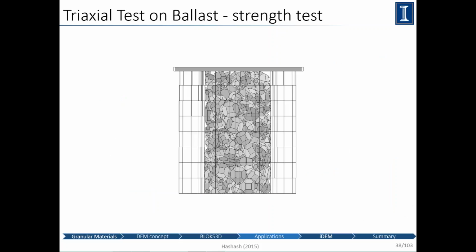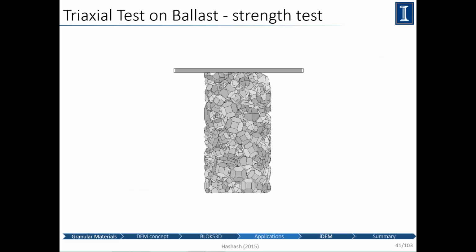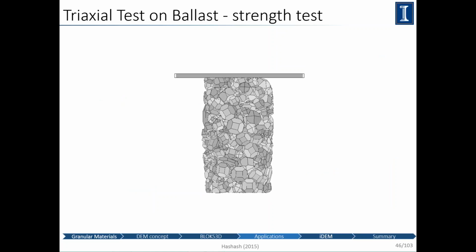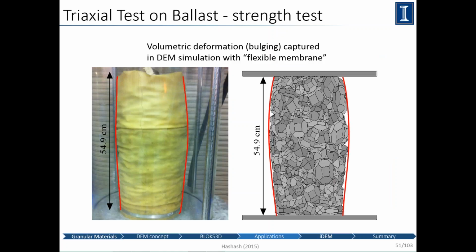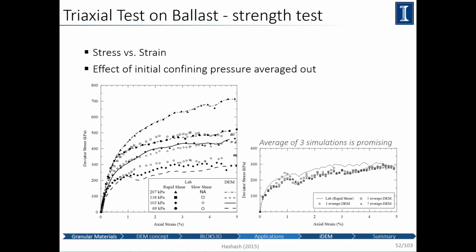And this is a simulation of how these things look like, the type of simulation we have. And let's see, the shapes don't look terribly bad. And then the computed stress strain curves look also reasonable. Notice that whether you're looking at the data or the DEM, you see jumps. And why do we have jumps a little bit in the data? Because you have particles, and as you shear, sometimes you overcome the friction and they suddenly move. And that's why you have these jumps.